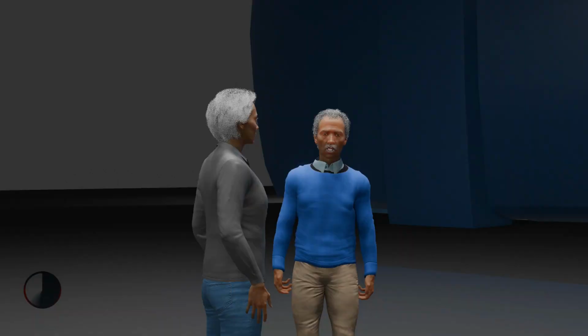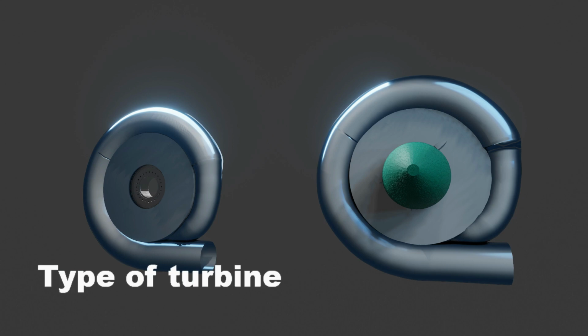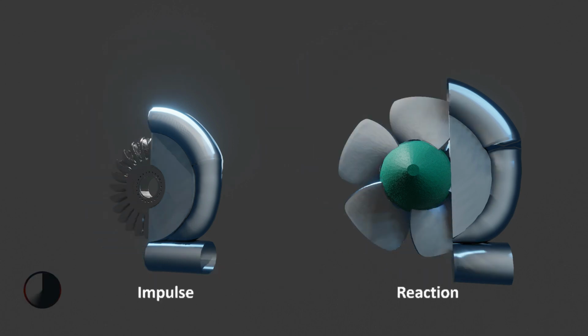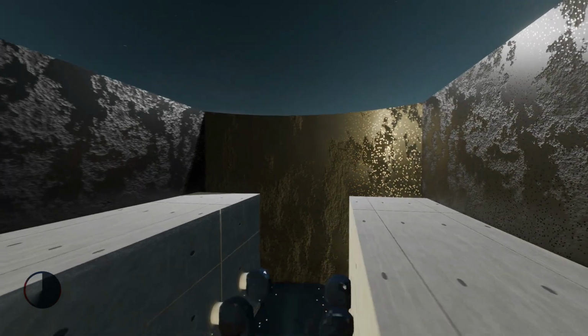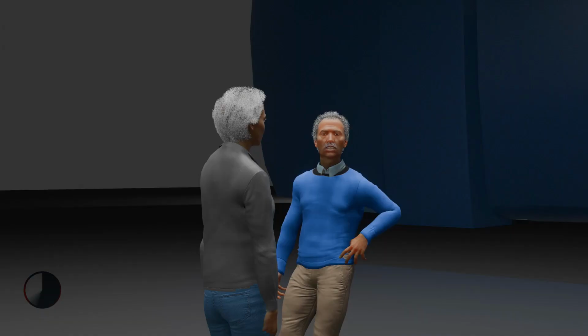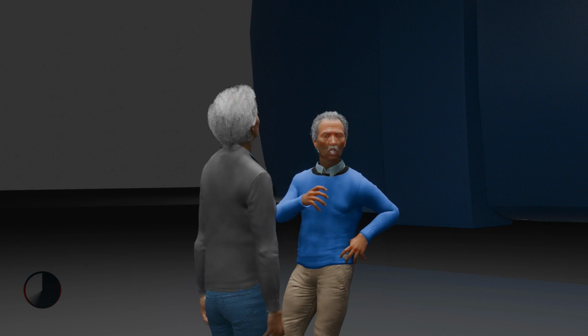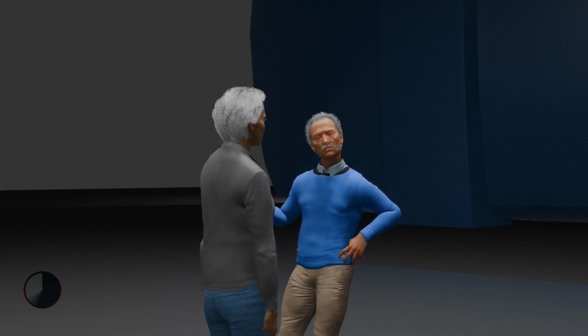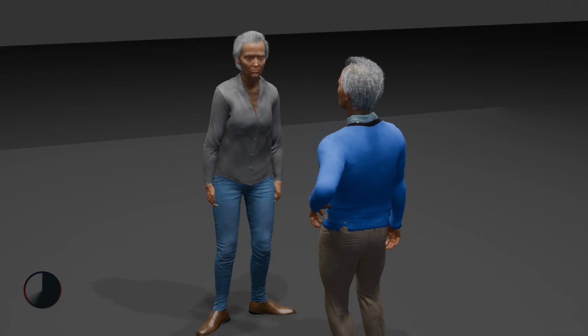It is on this note that there are two main types of hydropower turbines. These are reaction and impulse turbines. The type of hydropower turbine selected for a project is based on the height of the standing water, or the volume of the water over time at the site. Other deciding factors include how deep the turbine must be set, turbine efficiency, and cost.